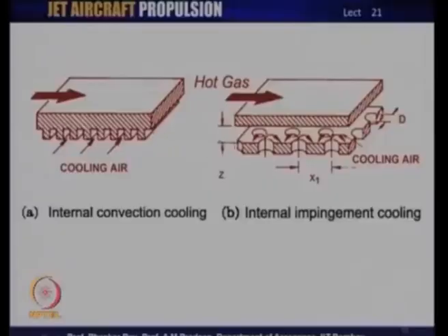The next method which came into being, and which is used typically in the front side of the blade, that is the internal side of the leading edge of a blade, is the impingement cooling. Now, let us see how it actually works.